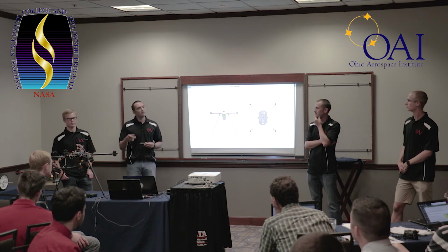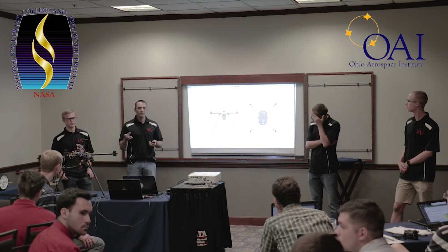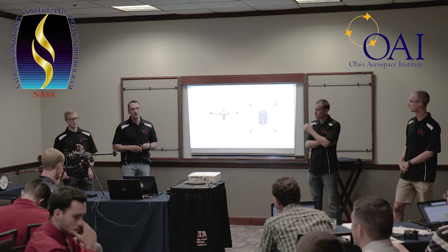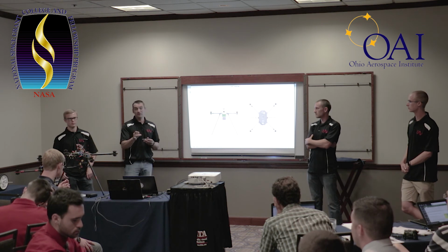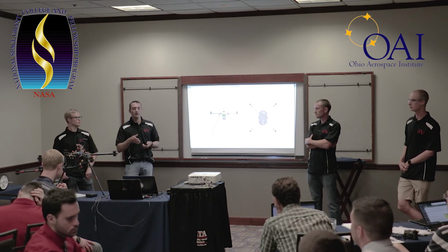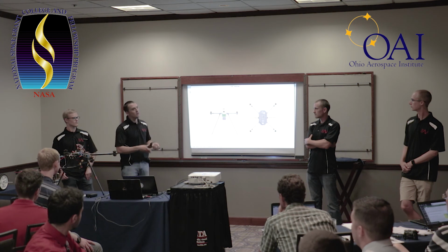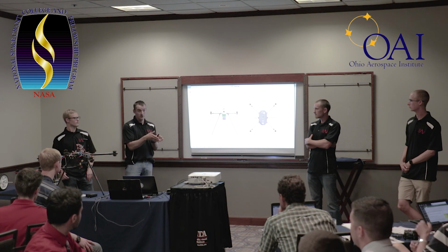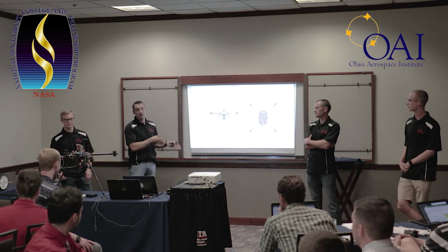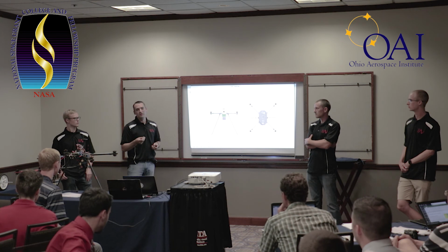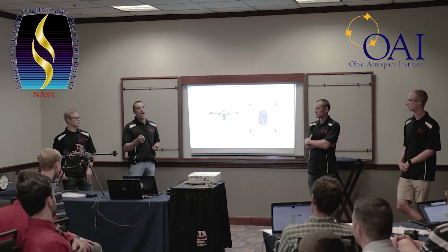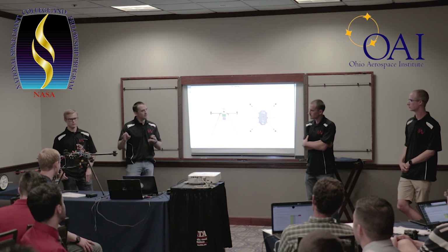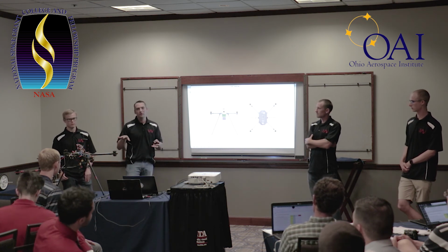I think the biggest thing is this is our third iteration at something like this. We built a much larger platform. We've discussed a little bit off topic tonight, but all of these started with thrust measurements. We built a thrust stand on a linear actuator bearing, so we were able to actually test coaxial motors and see what thrust they actually produce combined. That metric was the number to have, to say, hey, I can build this platform, I can have this all up weight, and I can have this kind of fault tolerance or error issue and still be safe.